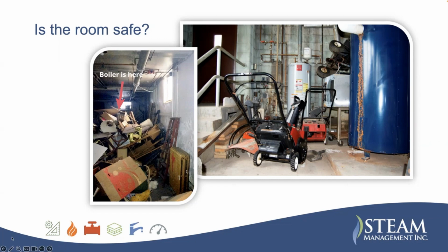And then I saw the cross that he put on the radiator. I'm thinking he probably put that on there in case something happened, look back here for me. The other thing, this is my church, and they never listen to me, right? I said, whatever you do, don't put gas powered equipment or gasoline inside where the boilers are. The reason being is that gasoline fumes are heavier than air, and they'll go right along the floor and then get sucked into the boiler and cause it to catch fire. So look around the boiler room, make sure it's safe inside there.